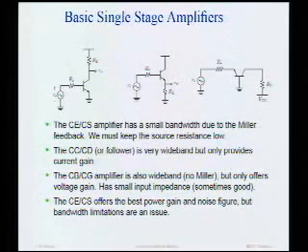What are some other problems with a common source amplifier? Anyone? It's all review material, right? Why not just go out and build all our amplifiers with a common source amplifier? Use low source impedances so we have lots of bandwidth. Yes, Mike. I don't quite remember exactly, but it has to do with output impedance. Okay, that's a good point. Let's not worry about that now. We could always buffer. We could put a buffer in there and get any output impedance we want.